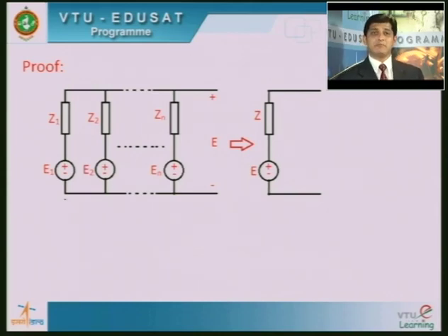And one more assumption that we make when dealing with node analysis is that unless there is a current source which shows the current to be entering the node, we consider all currents to be leaving currents. Now see, in these branches, do we have any current source which is showing the current entering the node? No. We only have the voltage sources along with these internal impedances, no current source showing the current entering the node. That means no entering current is present, so all the currents that we have here in n number of branches are leaving currents.